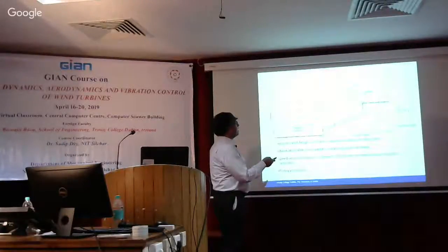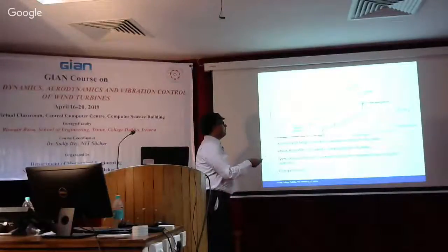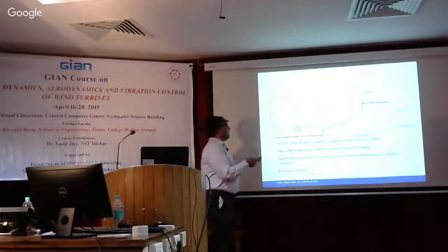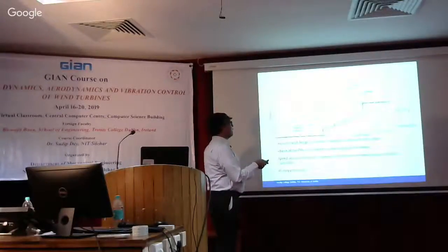And then, say for example, beyond the point where you're saturated. So from here, C, your wind speed goes up. In that case, your point should be somewhere here. So instead of going here instantaneously, you go from C to C1, and then if there's a further increase in wind speed, you saturate the power or torque over here, the generated torque. Because your generated torque times the speed gives you the power. Okay? So if you take a multiplication of this torque and the speed, that gives you the power. So you keep on ensuring here that you have an optimal power.